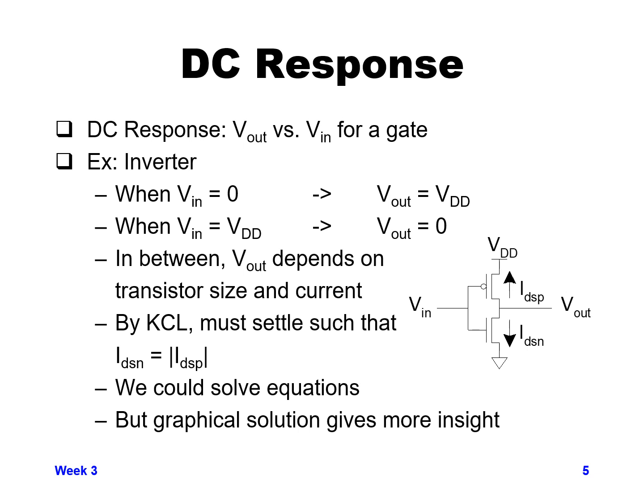We've just seen in the previous discussion on pass transistors, there could be situations where you're not fully at 0 or VDD. But let's look at an example here. If we have an inverter, when Vin is 0, that means that the NMOS gate is fully turned off, PMOS gate is fully turned on.